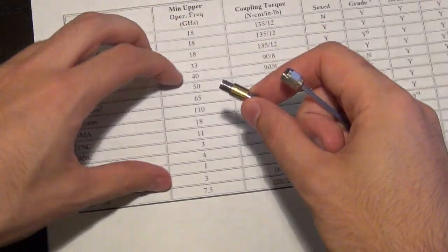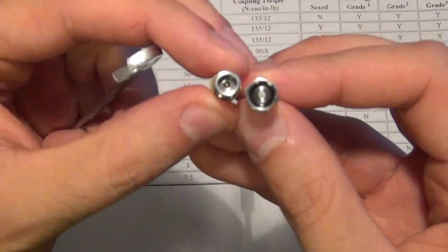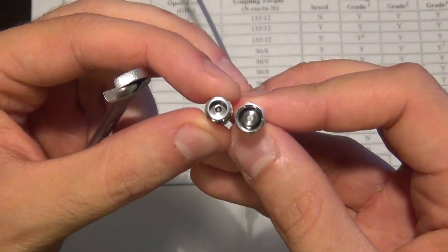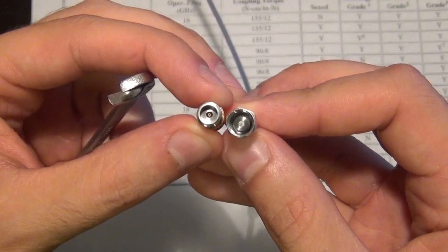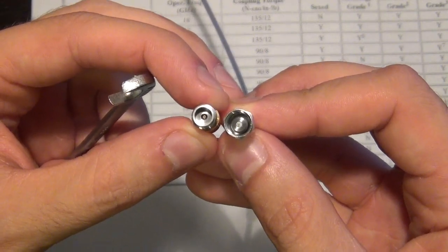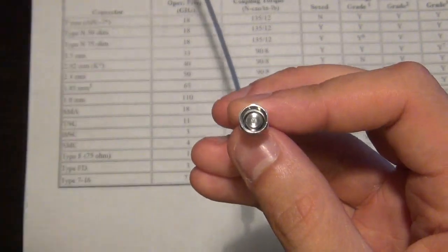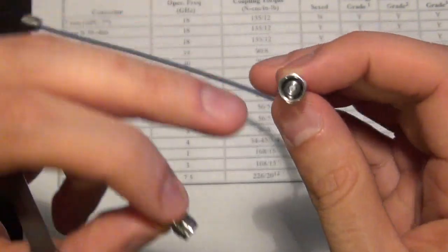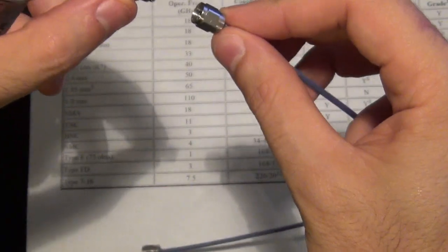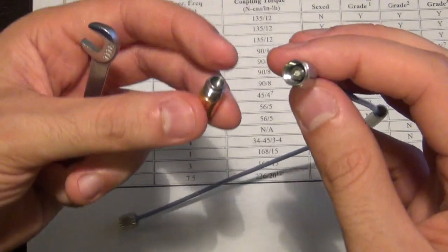The other thing you need to make sure of is to always examine the connectors before and after you've used them. Make sure the pins are perfectly centered. Make sure the connectors are completely clean. There's no dirt or debris in there. If, for example, the center pin of the male connector is bent, throw the cable away, because you should never use it with another connector. If this center pin was bent and I try to screw it into this connector, I will end up damaging this connector also, and they'll both have to be thrown away.